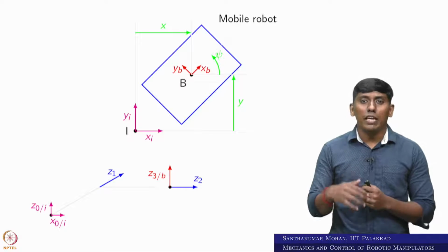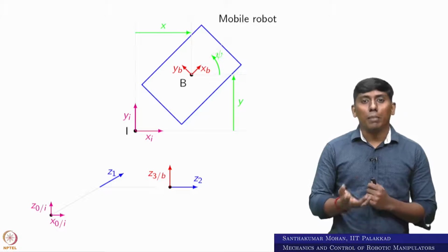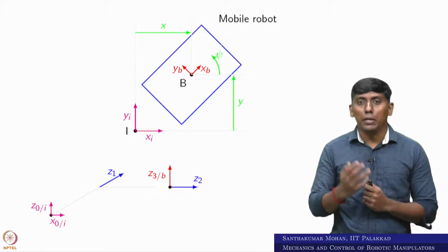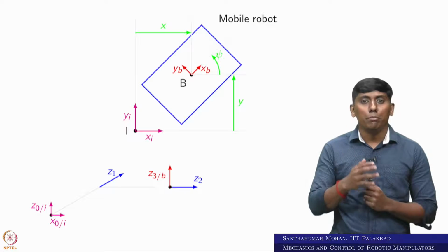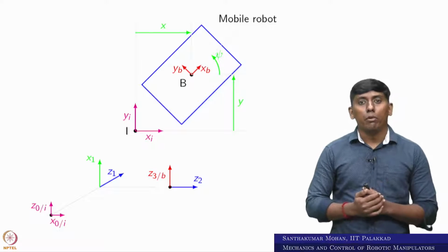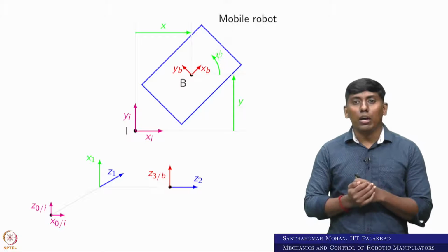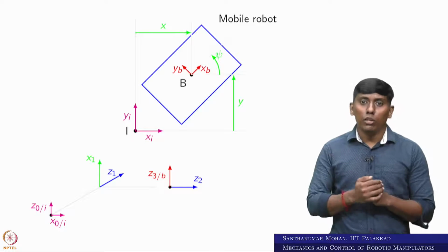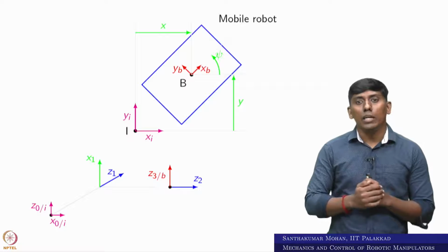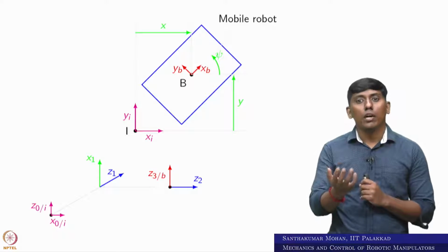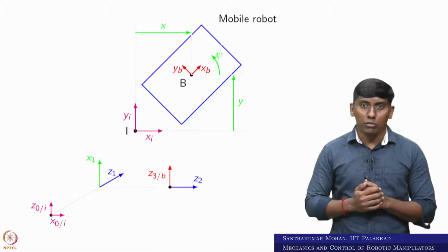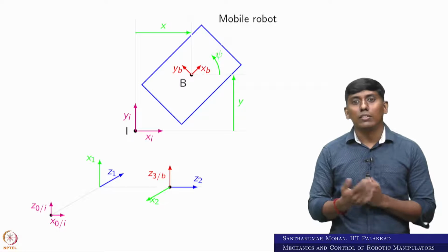Once you obtain that, in the same way you can go for x1. The plane containing z1 and z2, the perpendicular to that, can come upward or downward. I took it as the upward direction for x1. Similarly, for z3 and z2, the plane is on the screen, so the direction piercing the plane, coming outward, can be x2. I have taken coming out as x2.